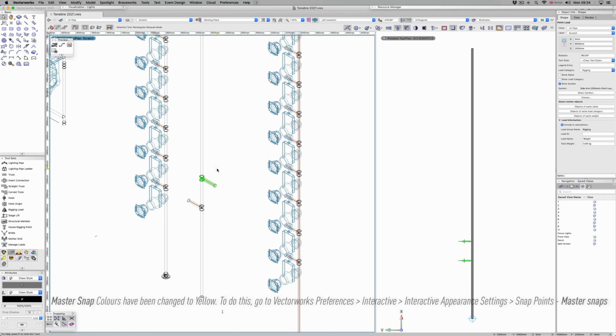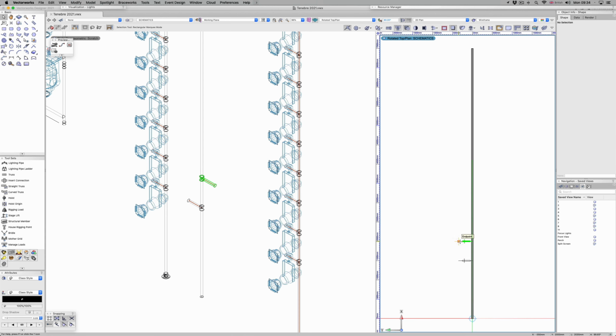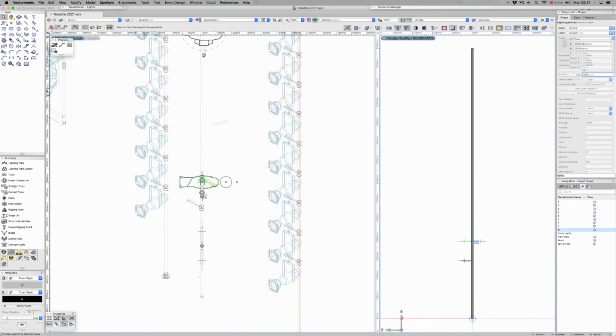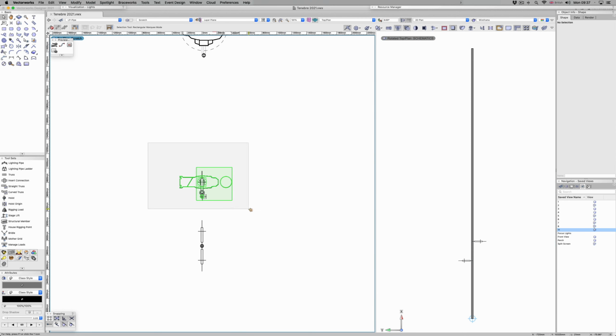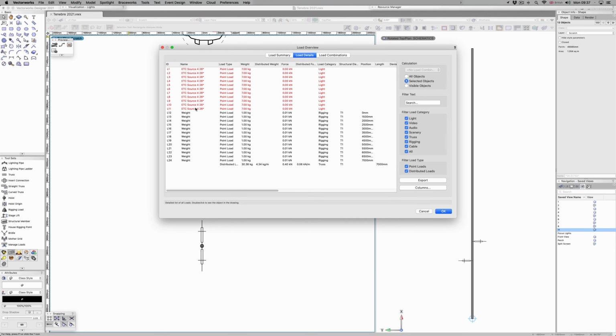There is a snag with schematic views in that all objects are created in their unrotated state. So even with this method, there is still a bit of housekeeping to do. The problem with using the lighting pipe tool on its own is that the lighting pipe does not associate the lighting devices when it comes to any load calculations. This is because the lights are offset by more than the width of the pipe. This may be of little importance to you, and in which case this lighting pipe method is definitely the way to go.